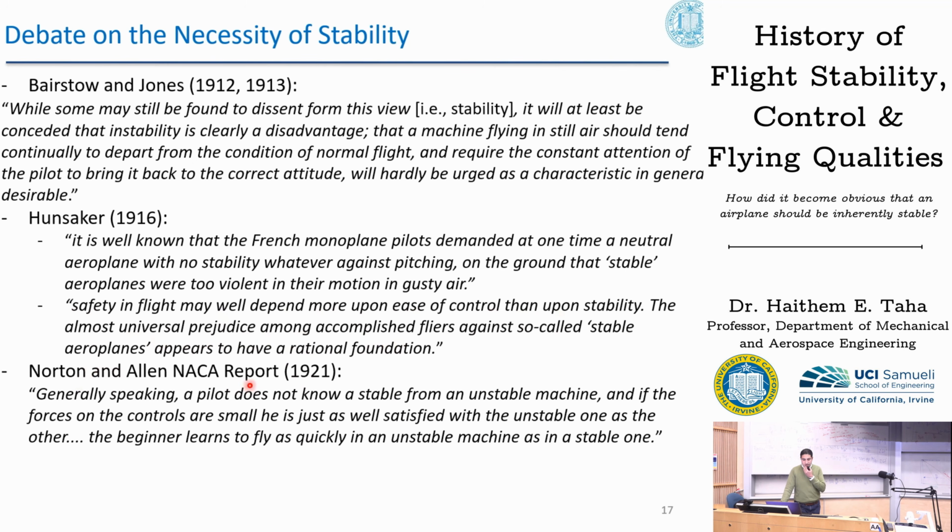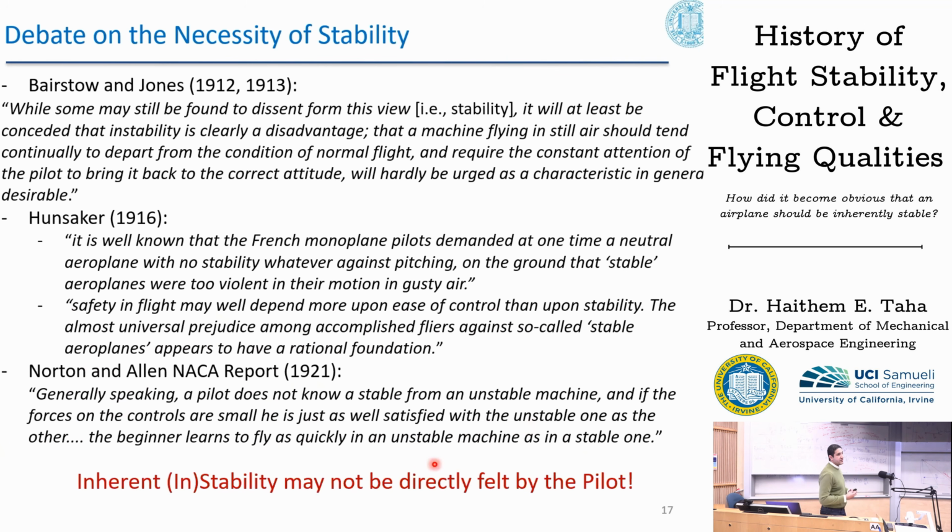In their 1921 NACA report, Norton and Allen said, generally speaking, a pilot does not know a stable from an unstable machine. And if the forces on the controls are small, he is just as well satisfied with the unstable one as the other. The beginner learns to fly as quickly in an unstable machine as in a stable one. So they are referring to an interesting point that the instability of the airplane may not be directly felt by the pilot.